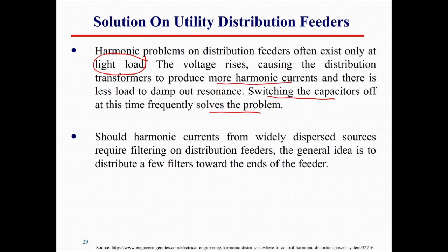Should harmonic current from widely dispersed sources require filtering on the distribution feeder, the general idea is to distribute a few filters toward the end of the feeder.